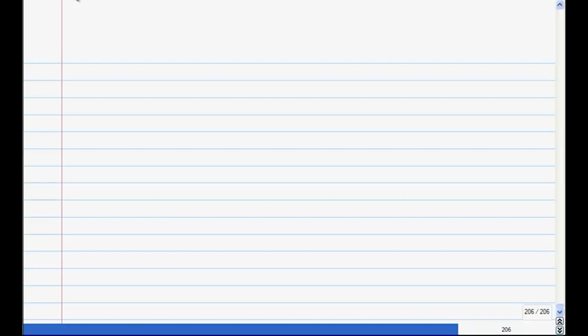We have spent quite a bit of time on first order circuits, but we have also generalized some principles from there which will be applicable to higher order circuits. Everything that we said so far, you can use to analyze any circuit with a single capacitor or a single inductor. When I say single capacitor or inductor, it's assumed that you have done all the parallel and series combinations possible with the source being null. With the source being null, you will effectively get a single capacitor or a single inductor. That is a first order circuit. All of that you can analyze now with what we have.